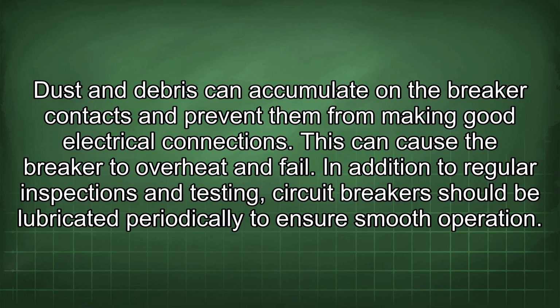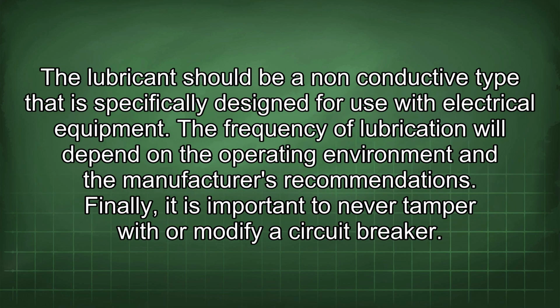In addition to regular inspections and testing, circuit breakers should be lubricated periodically to ensure smooth operation. The lubricant should be a non-conductive type that is specifically designed for use with electrical equipment. The frequency of lubrication will depend on the operating environment and the manufacturer's recommendations.